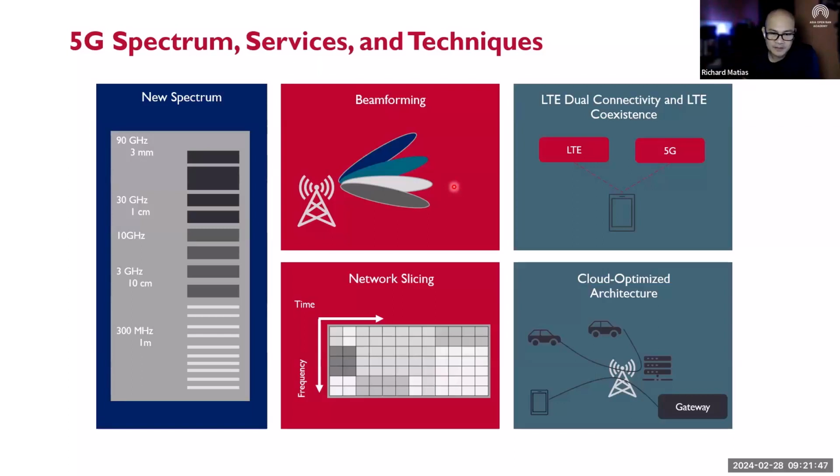Previously, what we were doing was physically changing the panning of the antenna or down tilting the antenna. But in this case, if we use artificial intelligence in 5G and then use Open RAN, the system can identify where the subscribers are located. And then it can focus the beam on that specific subscriber or group of subscribers by itself. Okay, so using that artificial intelligence. And of course, the beamforming technology.